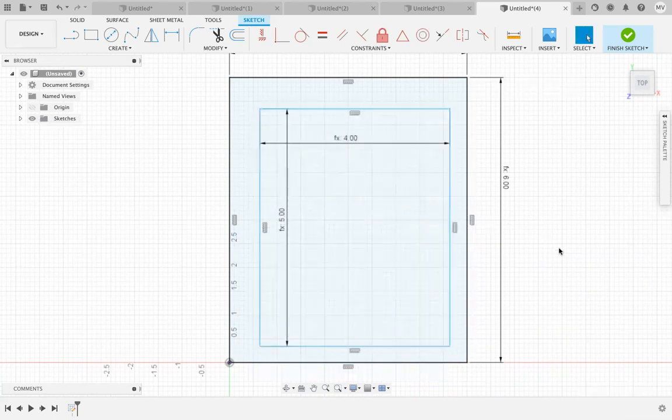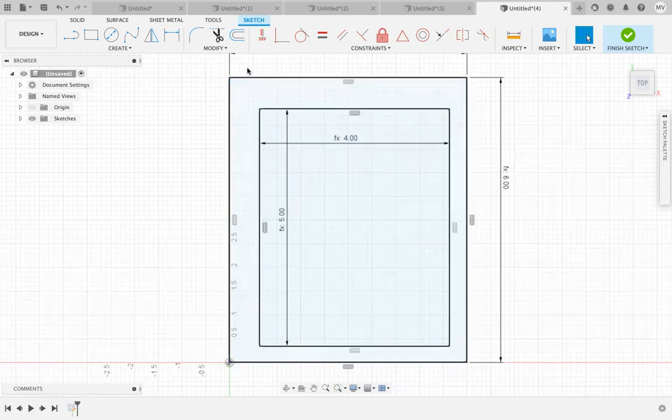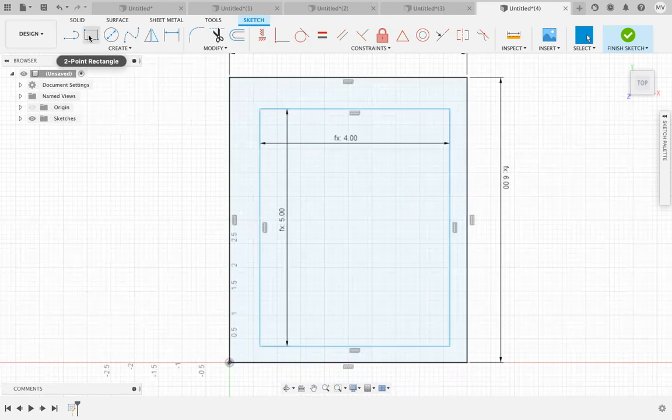So how do we do this? I'm going to show you a way to do it, and then I'm going to redo everything I just did way faster and a little more efficiently. Okay? So one thing we can do is just say, all right, this corner should always be thickness away from the left edge and thickness away from the top. I could place a rectangle here. See that little box there that's popping up? That box is telling me I'm constraining this new rectangle to the corner of that big black rectangle.